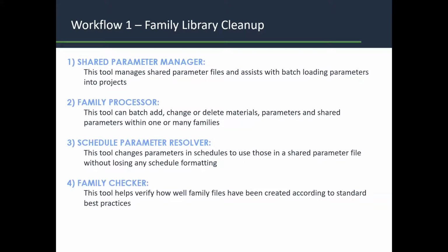Third tool we'll take a look at is the Schedule Parameter Resolver. This tool changes parameters in schedules to use those in a shared parameter file without losing any schedule formatting. So as you know, if you were to manually remove a project parameter and then add a shared parameter, this takes time and removes the schedule formatting already in place. So Shared Parameter Resolver simplifies this process into one single step by replacing the parameter with the desired shared parameter.